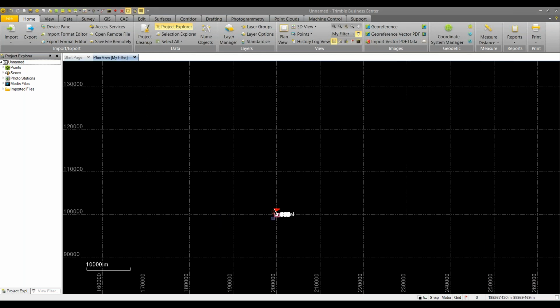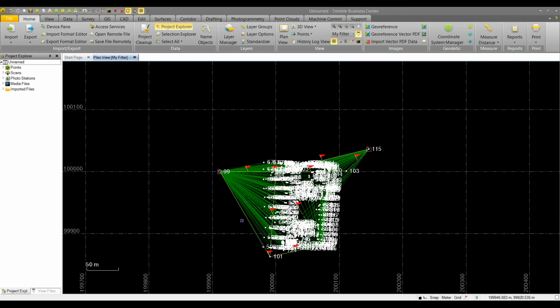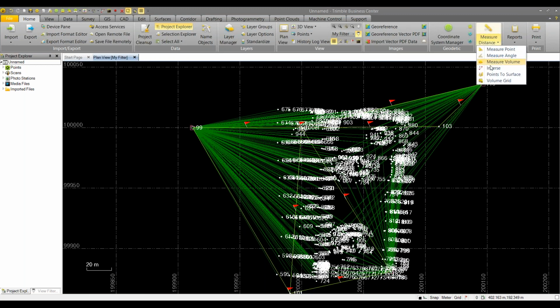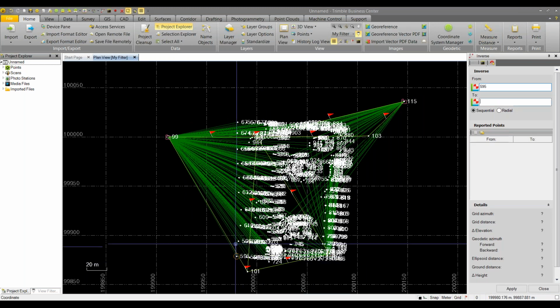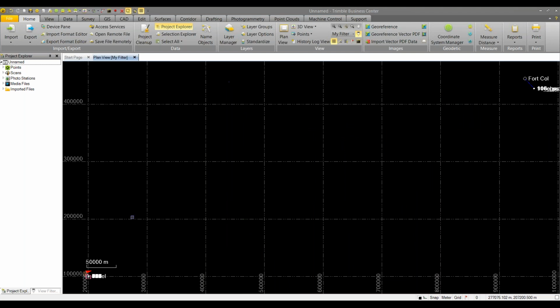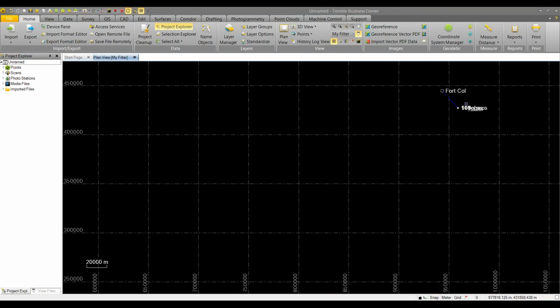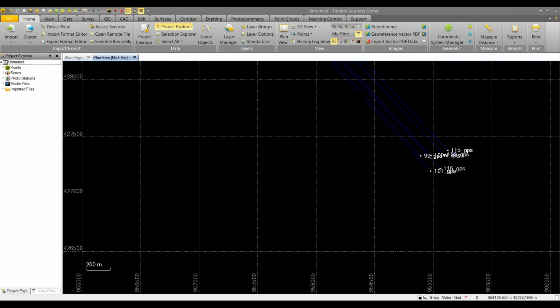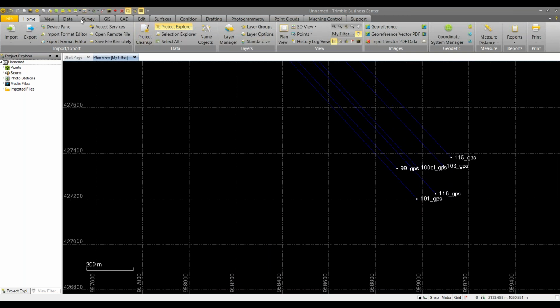So that gets automatically updated. If we go back to our total station work, and we do that same inverse again, we'll see a difference now between our grid and our ground, and that's because we're now applying this projection. So our grid distances won't be equal to our ground. But we're going to calibrate this site, and we want our final result to be in ground. So the first thing we're going to have to do is a local site settings.